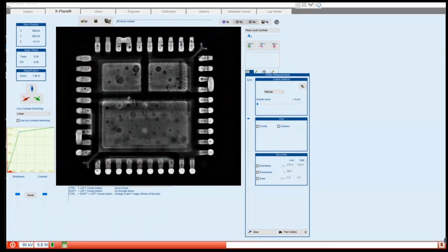So you may be thinking, well, what's the point of this scan? Because the results are not amazing. Yes, to achieve the amazing results, you need to do the longer scans, but in 40 seconds, those results are very good. And the point of this is to really now allow our customers to do these super fast scans to just quickly understand how many layers they are in the PCB, how many layers there are to a component, and to just very quickly do voiding analysis.